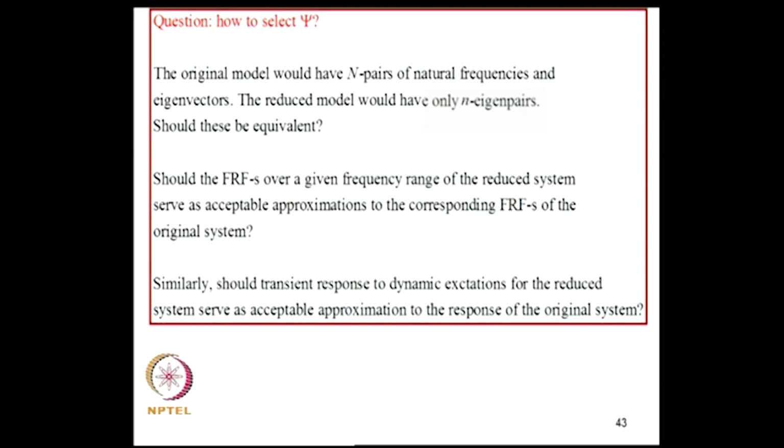Similarly, mode shapes, and we can also ask this question on the frequency response function between two coordinates. For example, should the frequency response function over a given frequency range of the reduced system serve as acceptable approximations to the corresponding FRFs of the original system? What is the objective of model reduction? That we have to specify. Similarly, if you are interested in transient behavior of the system, should transient response to dynamic excitations for the reduced system serve as acceptable approximation to the response of the original system?